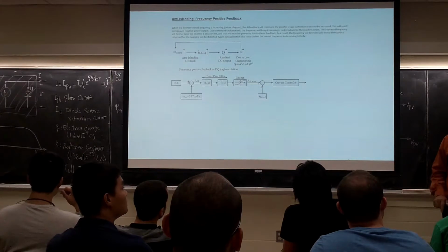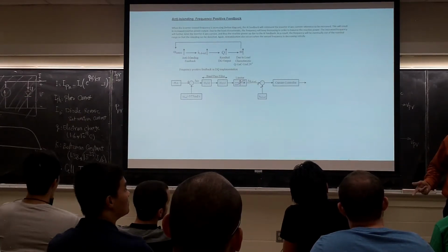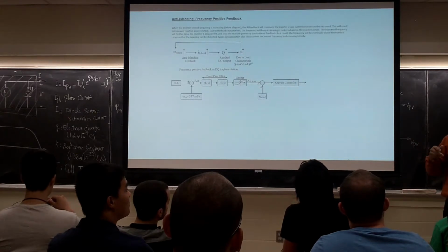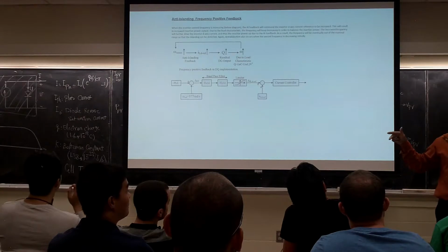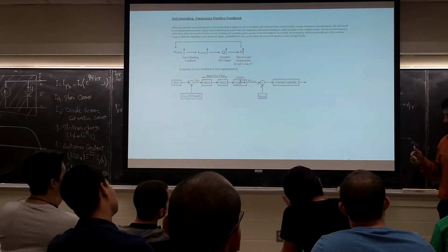Because if you don't disconnect, the utility thinks the grid is off. If they are going to, for example, work on it, they assume the grid is cold now, that it's not powered up. But you are there. Somebody goes to touch the network, the grid, thinking it is off. It's not, because you are generating. Now, you need to shut down.